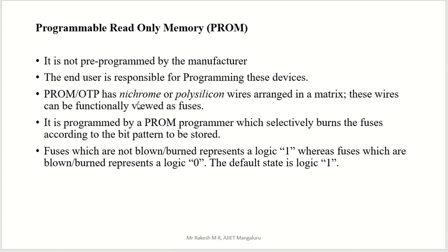PROM has nichrome or polysilicon wires arranged in a matrix. These wires can be functionally viewed as fuses. We are going to use nichrome or polysilicon wires in rows and columns, and we are going to store some bit information in those wires.